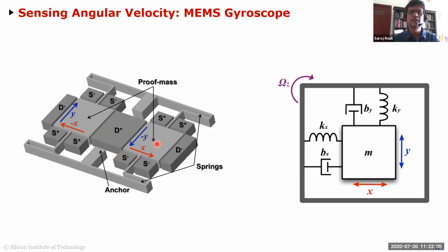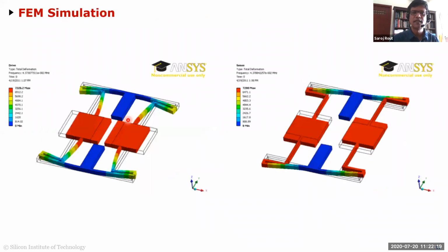So when you rotate, what happens is, again, the same thing. These mass spring systems are actually vibrating at a certain frequency, and the amplitude of that vibration starts changing, which is proportional to your angular velocity. And this is showing a finite element simulation method to simulate, when you're doing angular rotation, how the separation between the masses changes.